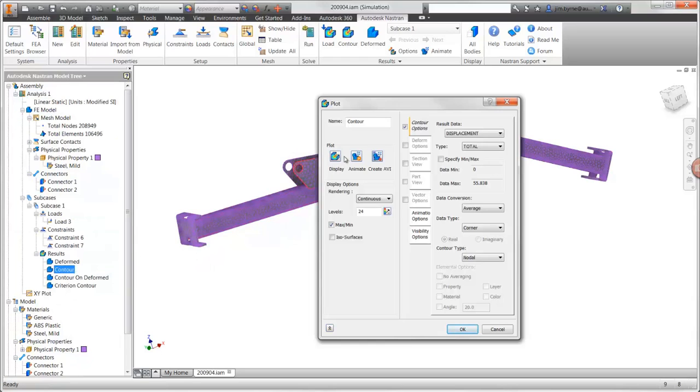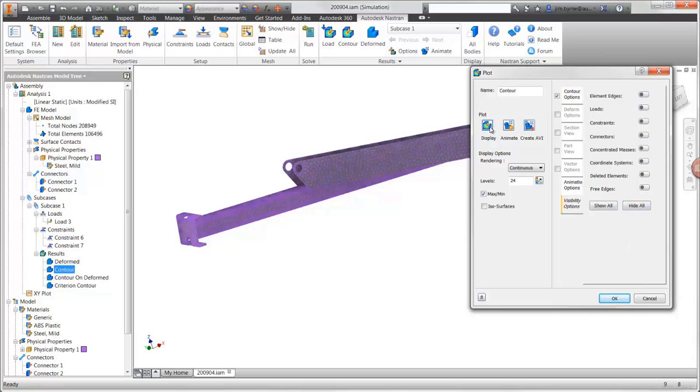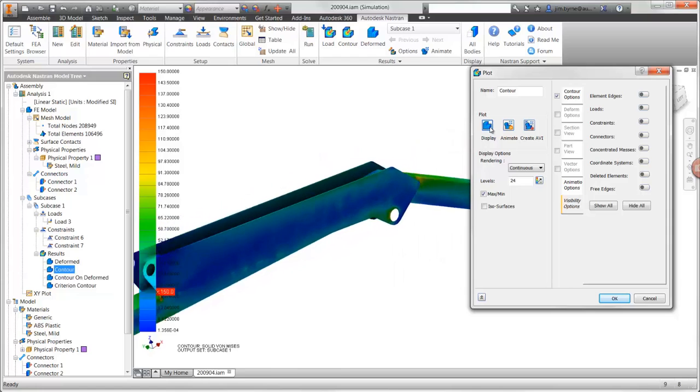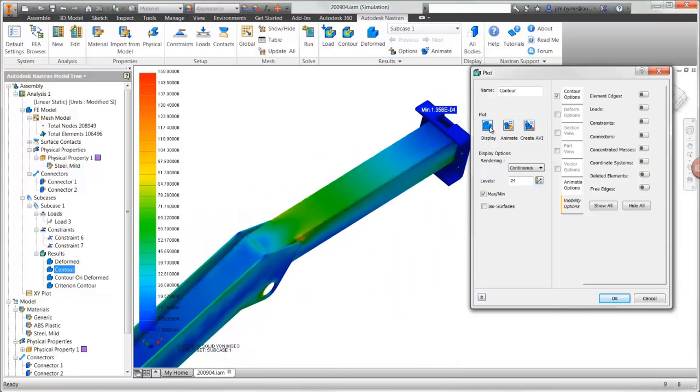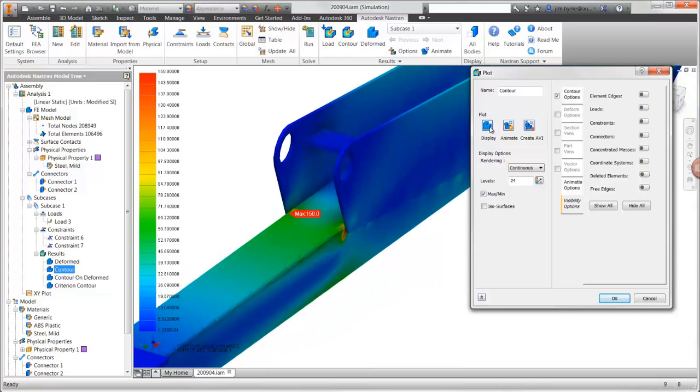There are many plots available for viewing the stress on the model. We'll start with the von Mises plot to find areas of high stress concentrations. Before displaying the plot in the graphics view, we can already see the highest value in the legend is more than 300 megapascals. As we pan over the model, we're observing most of our concern is on both ends of the actuator plate.